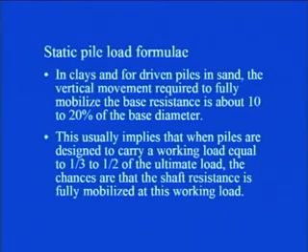This usually implies that when piles are designed to carry a working load equal to 1/3 or half of the ultimate load, the chances are that the shaft resistance is fully mobilized at this working load. So, usually what happens is that piles are designed to carry a working load equal to 1/3 or half of the ultimate load.